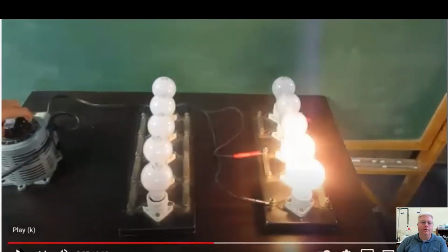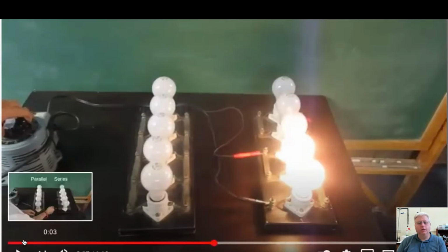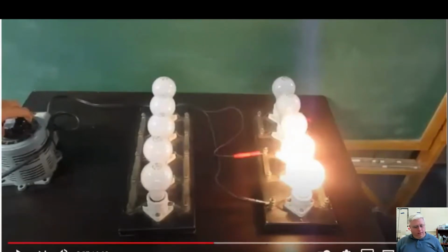All right, so now instead of 5 bulbs sharing 120 volts, because that's what we're plugged into, a power supply in the wall giving 120 volts. When 5 bulbs were sharing that 120 volts, they all got split up, right? 120 divided by 5 should be able to do this in my head, but 24. So they each got 24 volts.